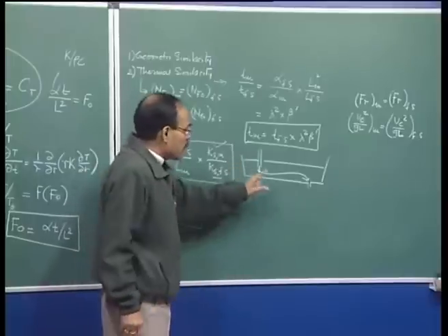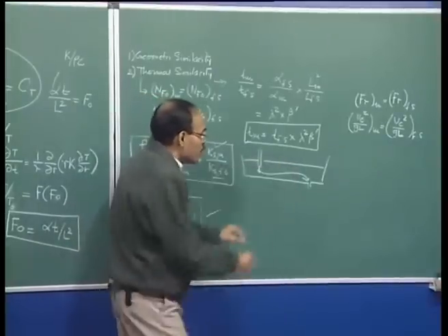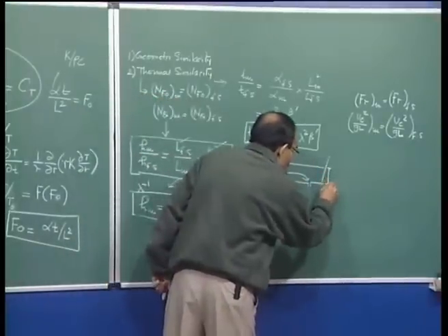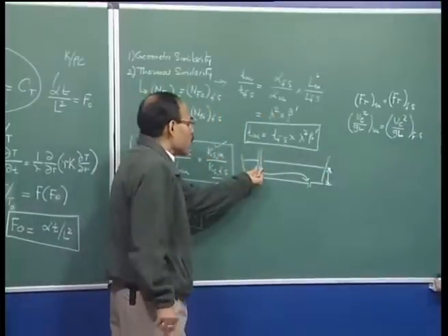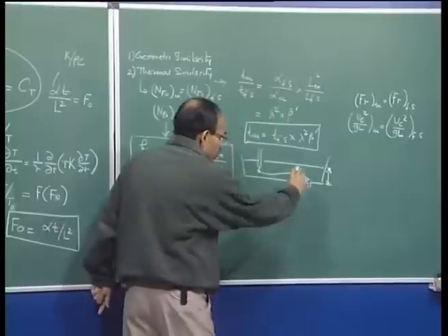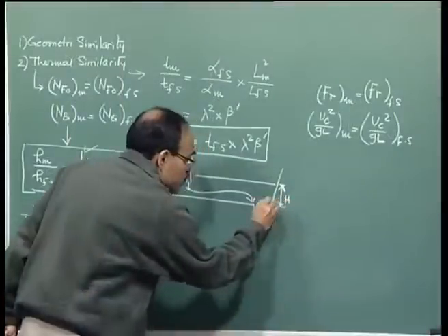In this case, the meaningful length scale is actually the depth of the liquid which governs the flow rate out of the tun dish under steady state condition. It is not the orifice dimension, but it is the depth of the liquid, H, which controls.